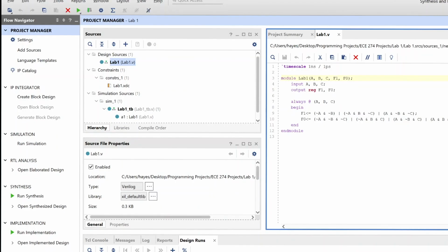Once you have written Verilog code along with an accompanying test bench, you are able to run a simulation to view how information moves through your code, or, more specifically, how zeros and ones move through the circuit to see if the desired behavior has been successfully captured.